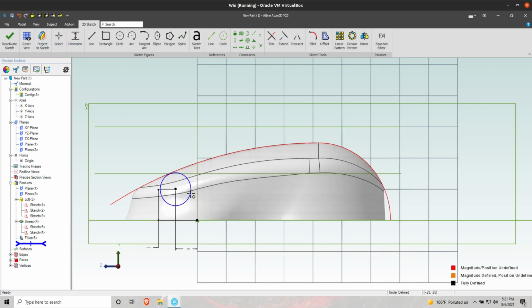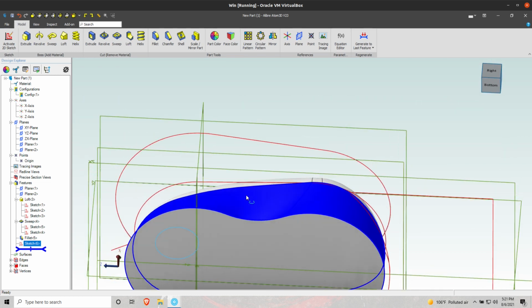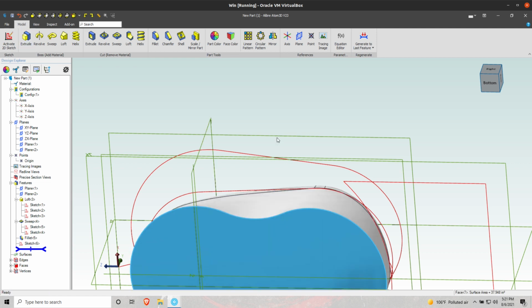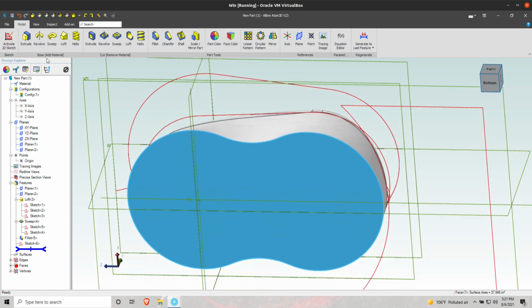All right, we're going to add a nice little scrolly wheel on there. And then let's go with 1.5 here, right? So that could be a scroll wheel. Before I extrude that, I also want to hollow this out. And when I make this hollow, I want to do it before I add more features so that it will shell to a consistent thickness, right? I'm not trying to make an actual mouse with all of its individual components, just the impression of a mouse for the purposes of this video.